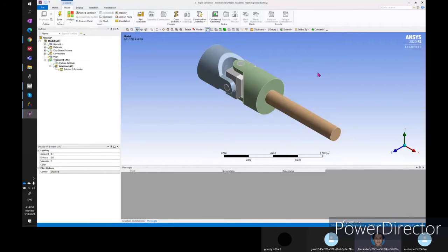To be safe, every time you import an assembly, assuming that you all have a CAD background, so you know what I mean by part assembly, it is always good to check whether they are completely imported. Sometimes some of the assembly parts go missing during the import.